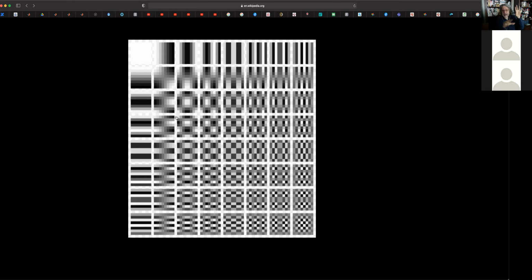If they are large, and if the others, the high frequency ones, are small, I can get rid of the high frequency content. And with the low frequency, it will be an approximation, but it will be a lossy compression. The loss is that I'm losing the high frequency content, so some detail will be lost, but I can get some really good compression ratios by only coarsely or approximately rendering my 8x8 image.